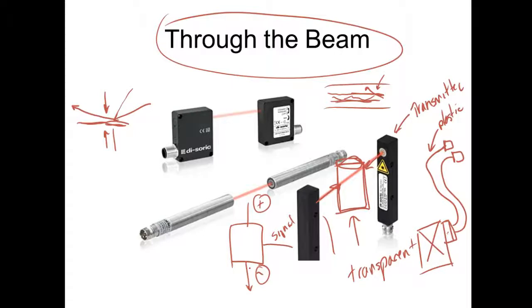They've even got cables that actually have LEDs on the cable connector itself, and those are really nice because what you got to understand is a lot of times you mount those sensors and you cannot see the indicator that's on the sensor, but you can see the indicator that's on the cable. So the cables cost a little more money, but what does it do? It makes them cheaper to maintain. So now you don't have to get yourself to see the indicator on that.